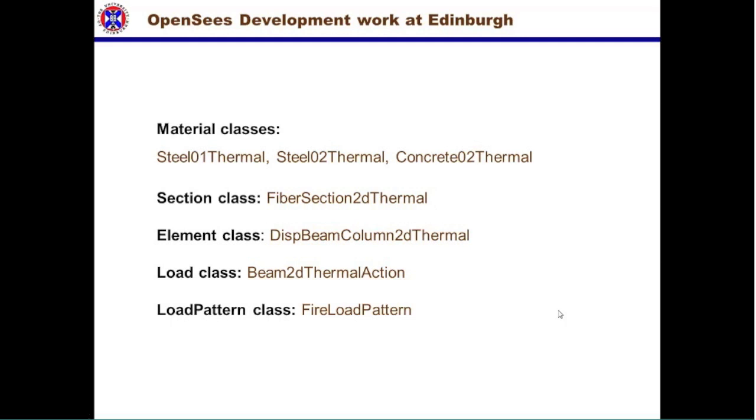Hello, everybody. I'm just here to introduce what we did in the OpenSees framework to bring the structural fire simulation capabilities in. As we know, to carry out the analysis, we need the material classes, the section classes, element classes and the load, which is the thermal action, and we developed the fire load pattern, which allows us to use a lot of thermal action loads.